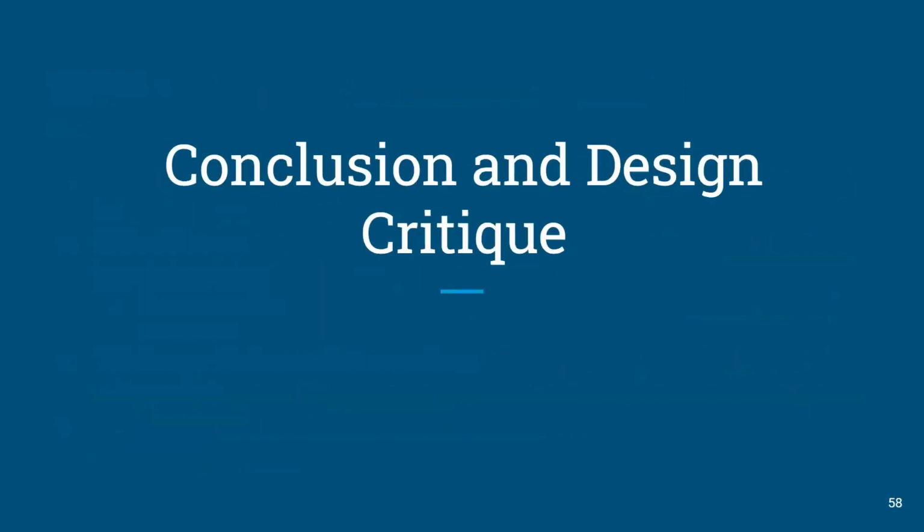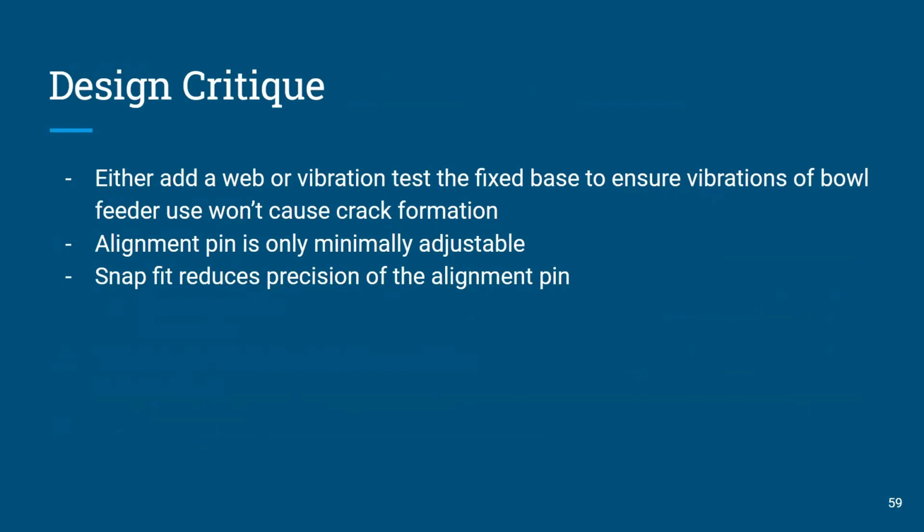Next, I will conclude the presentation with the design critique and conclusion. For design critiques, we would recommend either adding a web or doing a vibration test on the fixed base, because we reduced a lot of material in the modification for injection molding, and this would verify that the base does not form cracks. Another critique is that the alignment pin is only minimally adjustable, and another critique is that the snap fit reduces precision of the alignment pin compared to the through bolted holes.